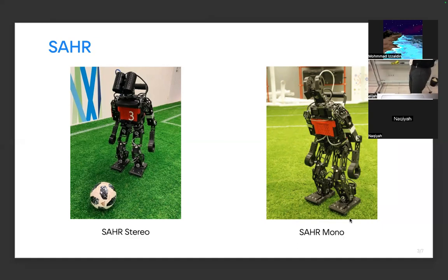The pitch is this motion in this vertical plane. Roll motion is this motion. And yaw motion is the motion around the vertical axis. Each leg has 6 servo motors. It has 3 pitches for hip, knee, and ankle.